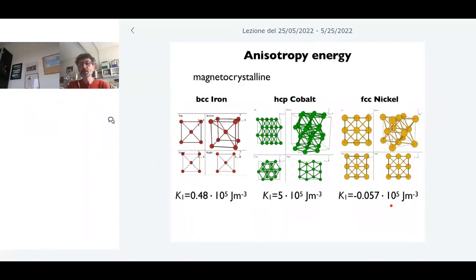And so you can immediately associate the idea of magnetic anisotropy with being soft or being hard. Materials that prefer a certain direction very strongly, and from which it is very difficult to leave that condition, are possible candidates for permanent hard magnetic materials.